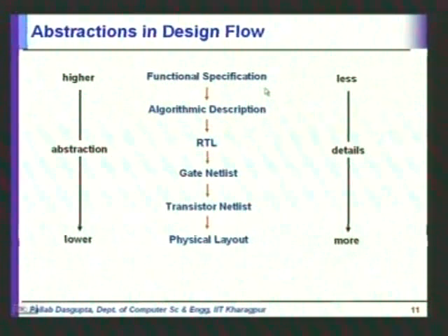And believe me, they are very important people, because of the technological advances, the synthesis process, the process of translating the design from the implementation to the final chip, has become mostly standardized, and there are very good tools available, and the room for optimization there is not very much, because you see it's the same set of tools which are being used by many companies. So all the innovation and the IP takes place at the architecture level.